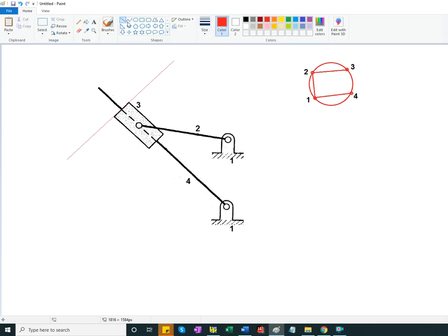So also connect, and I made this thinner. These two. Okay. So I can proceed with calculating any of the missing either 1, 3, and 2, 4 Kennedy lines. So let's go and find instant center 2, 4.